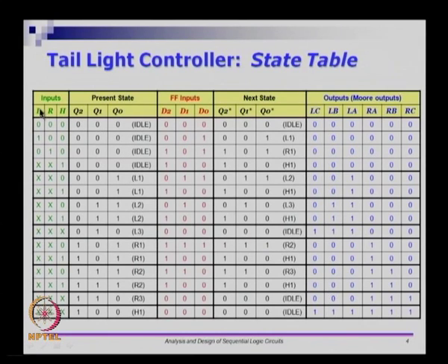Instead of looking at L or H which are 3 bits and Q2, Q1, Q0 which is 3 bits, ideally you should be writing 2 power 6 or 64 lines of the truth table, the state table. Instead, we are using the don't care conditions and concisely saying I do not care about L and R as long as H is 1, and if I am in the idle state, I should go to H1 state which is the hazard state, but I will still be producing all zeros as output because when I go to the state hazard 1, it will take care of blinking, right. So at idle I am supposed to be blank, at H1 all lights glow.